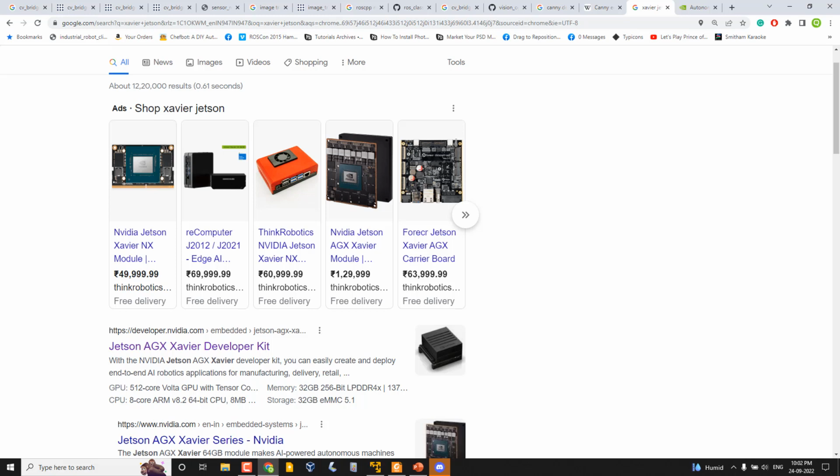You can easily prototype people detection on the laptop, as there are a lot of deep learning based applications available in Python. But if you deploy that on the Nano, it will eat all the CPU and RAM. It's very difficult, and we have to run this people detection along with navigation.